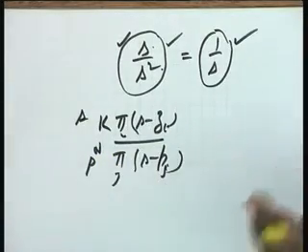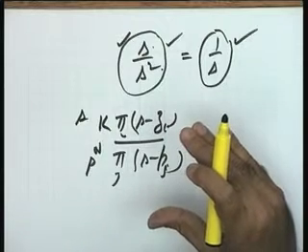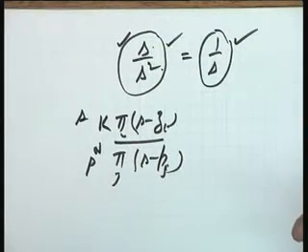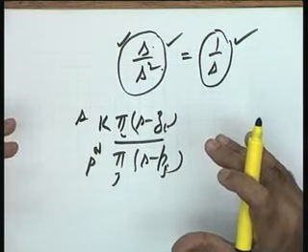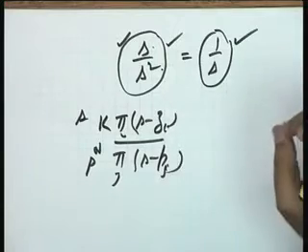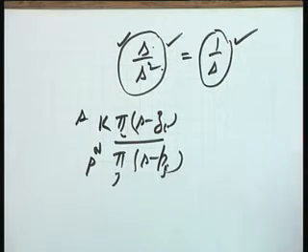Again, by pole-zero cancellation I mean, as far as the mathematical model is concerned, the perfect pole-zero cancellation. The statement about robustness which I made: the pole-zero cancellation in your mathematical model is not exact when you go to the actual system, but it approximates that value in the actual system as well, if the parameters do not wander too much around the nominal values. So this point may please be noted.